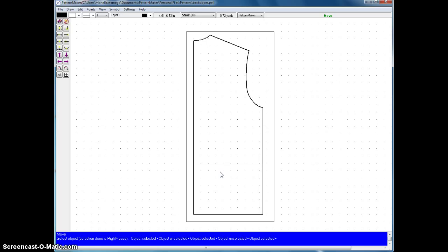Note that inside the sloper is not highlighted. This is because it is a different object and you haven't selected it. We want the waistline to stay with the sloper when we move it, so let's select that line too. The computer will keep asking you to select more items until you tell it you are done selecting. You should now have both the sloper and the line highlighted. Tell the computer you're finished selecting objects by pressing the Escape key, or you can right-click, select Done Selecting.